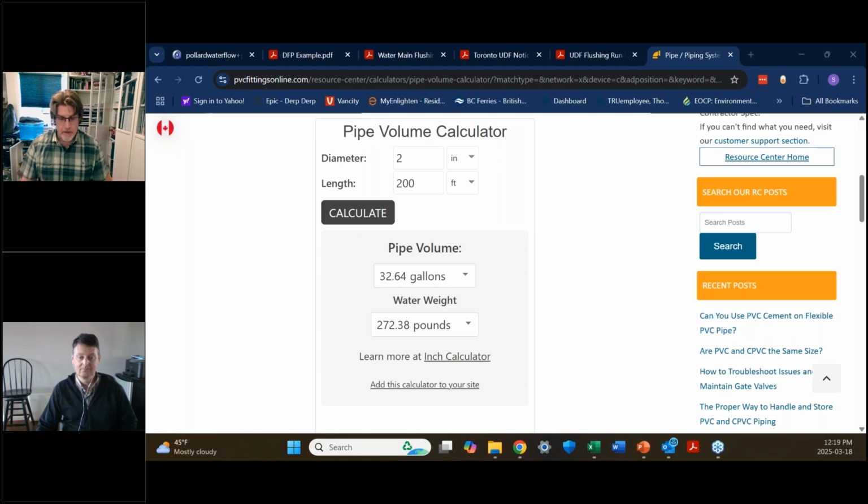So you do need some way to keep the flow directed so that it goes over the entire mat. Those ones are maybe a little bit simpler, but this is where we really recommend you try to get the ones that are integrated into the diffuser. It's just a better way to make sure that the entire flow is passing by the dechlorinator pucks.